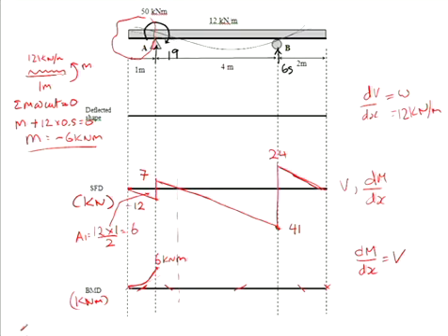But when you come back to this question, you would say, okay, I'm not going to use the area method. What I'm going to do is cut my beam again. I've got 12 kilonewtons per metre. I'm cutting it at 1 metre, and this time I'm saying I have my 50 on there. And at the cut, so maybe I'm cutting at 1.0001 metre. So I include the 50.